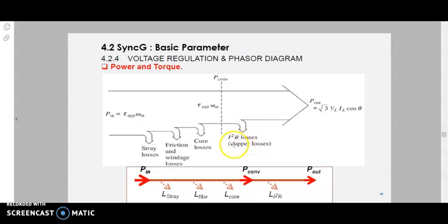After that, you subtract your core loss and copper loss. Copper loss means the internal resistance of your coil. The core loss is the mechanical loss of your motor or your generator, depending on how you construct your generator materials, so that contributes to the core loss. Meanwhile, copper loss is contributed by the selection or the size of the wires with which you build the coils.